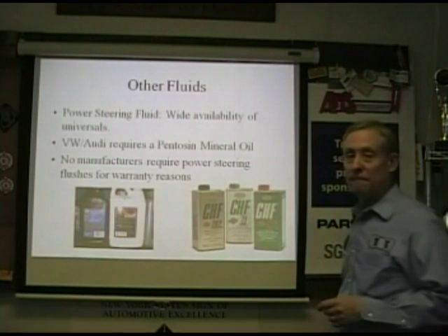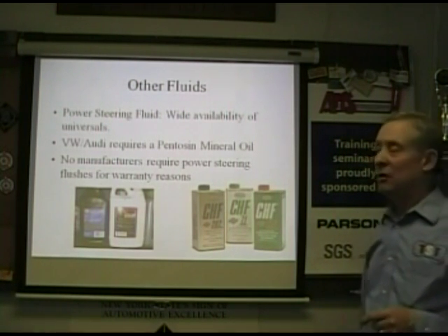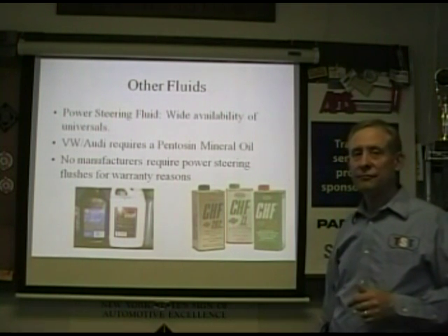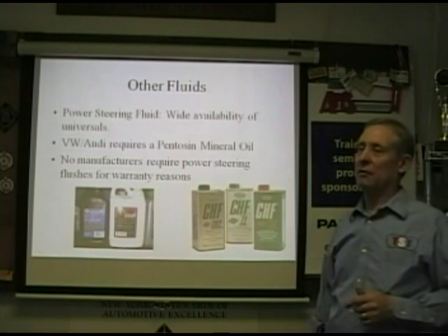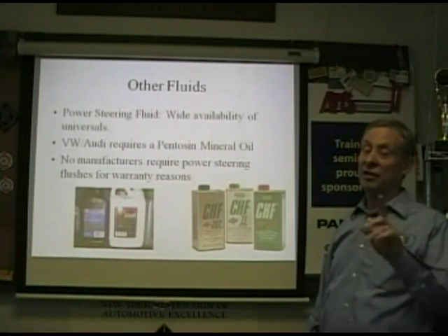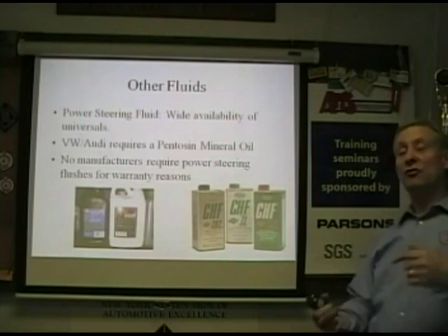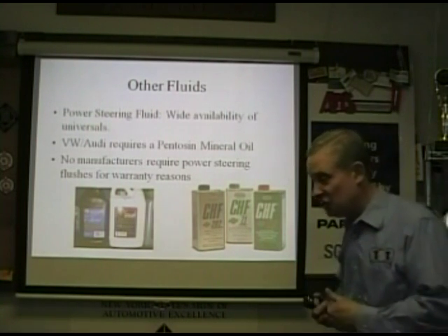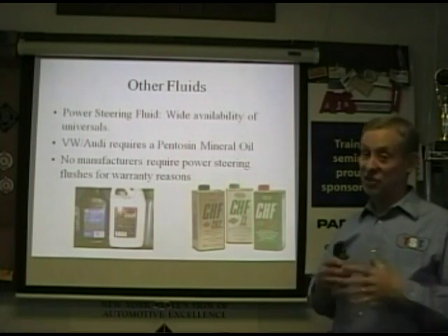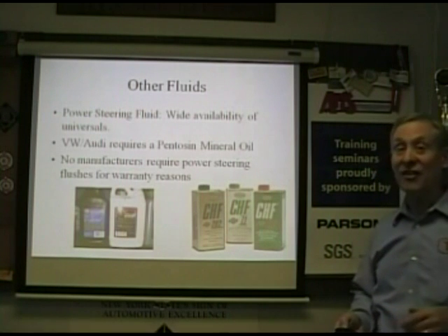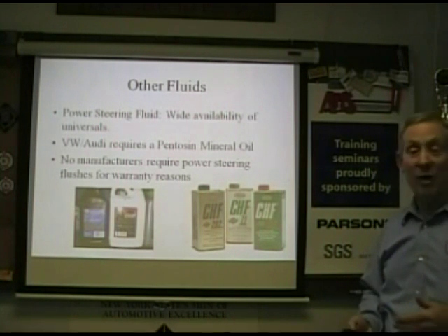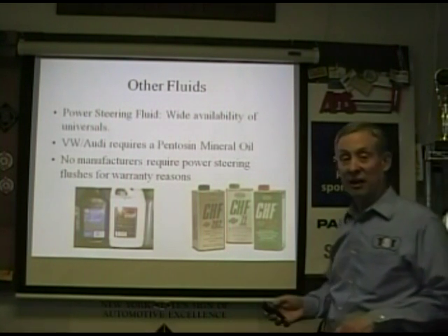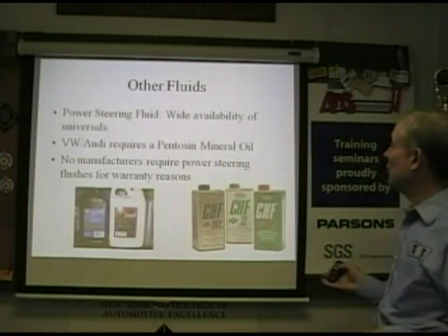And I guess we should also say you have to make sure you get all of the water or flush out of the coolant system to get a good fill. Actually, Jerry brings up a good point. If you're using a chemical flush, you got to make sure that stuff is gone. Can't leave any of that. Waste the water. Use the water. Yeah. Get rid of it. Flush it out. Make sure it's all clean.